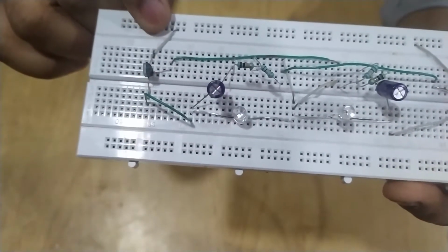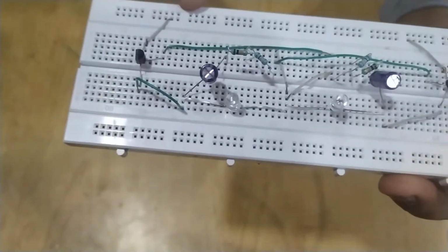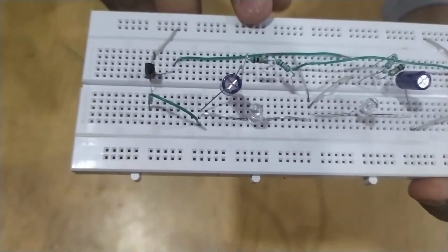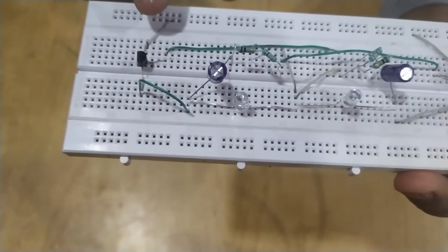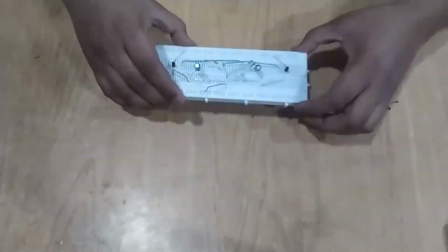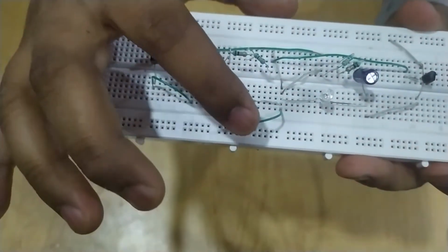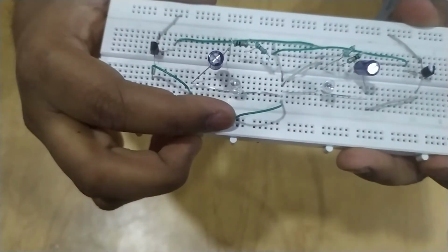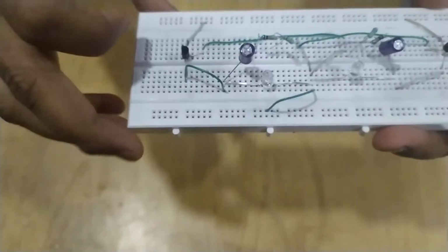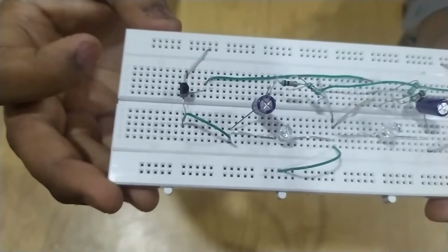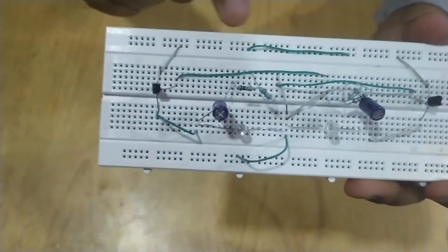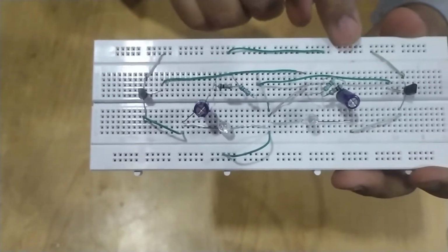So I've connected these to connect the emitter of both the BC547 to the ground. So I'm going to make this line as my ground terminal or the negative terminal. So I'm going to connect these two together also. So this will be connected to the power source, positive terminal, and this will be connected to the negative terminal of the power source. So I'm going to use one 5-volt source for the circuit. So I have connected one wire to short circuit these two rows.